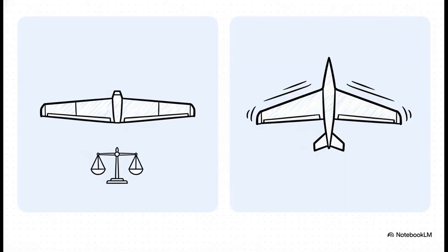To put that into perspective, a rectangular wing planform is super common on smaller general aviation planes, simply because of its highly stable characteristics. On the other hand, a tapered wing is what you use for planes that are operating at high subsonic speeds. But engineering is always a trade-off. While tapered wings are undeniably faster, they just don't have the desirable, safe stall characteristics that simple rectangular wings do.